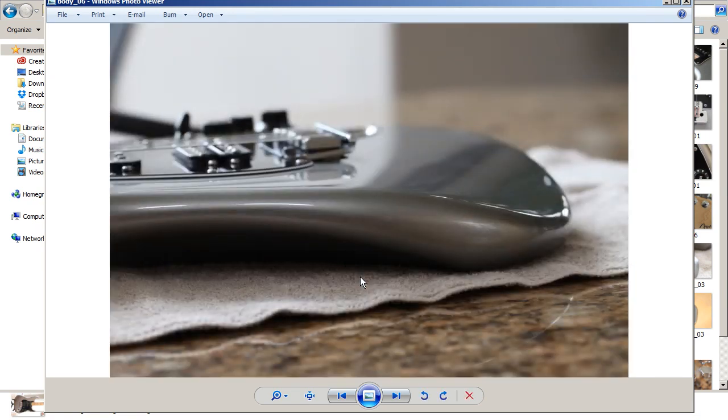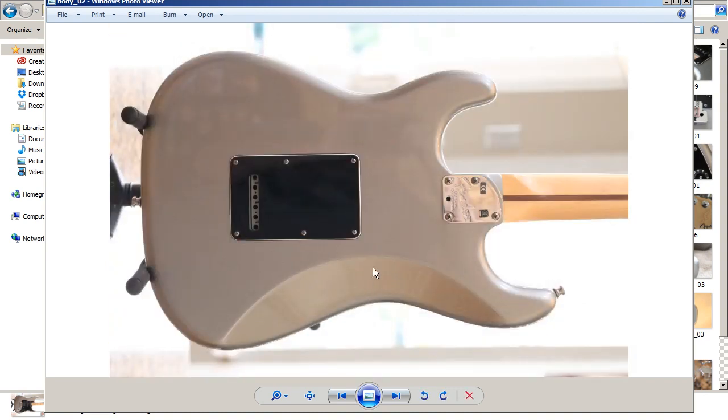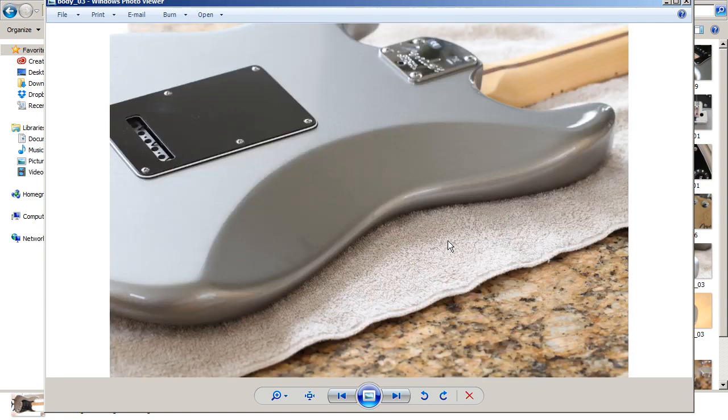All right, once all of that is done, then and only then will we start thinking about beveling this thing and getting some of these edges. We want to get all the primary forms done first before you do anything at all. Then we move to the secondary and the tertiary forms on the surface. If you take a look at this, we've got this nice big round bevel right here that really goes all the way around this thing, all the way through here and through there. But you'll notice right here, it tapers down and gets a little thinner. And it tapers right there and gets a little thinner.